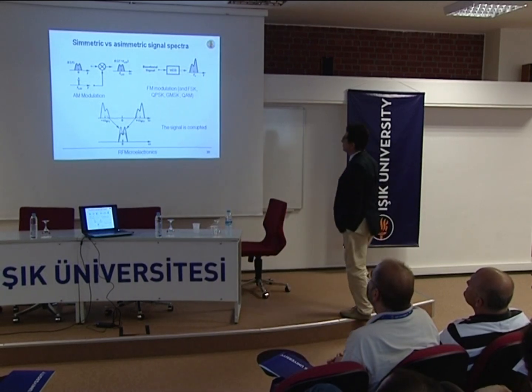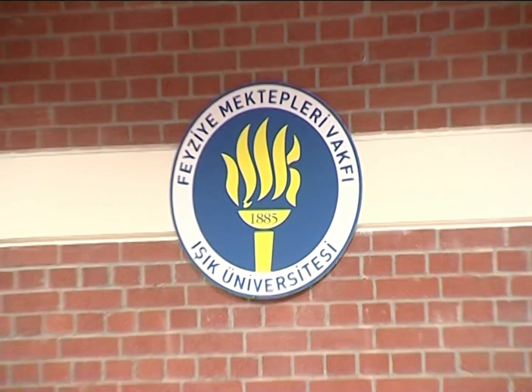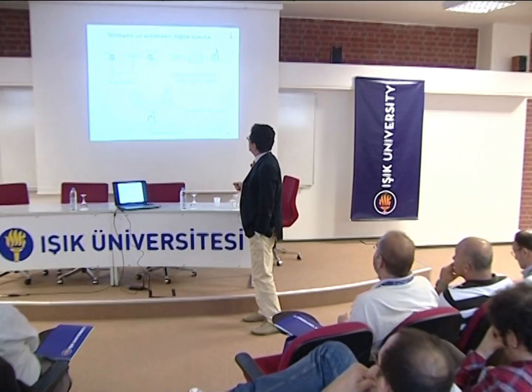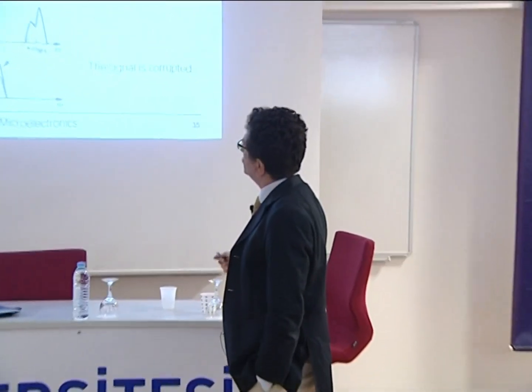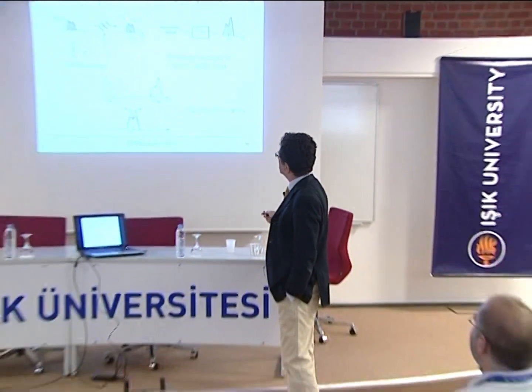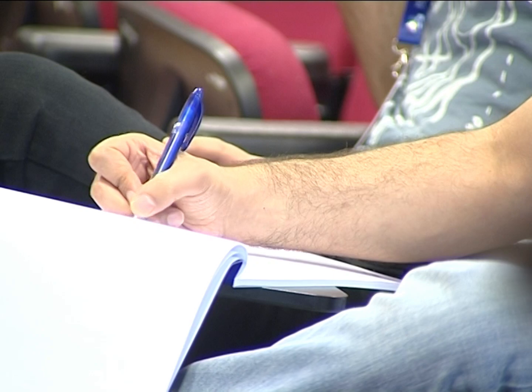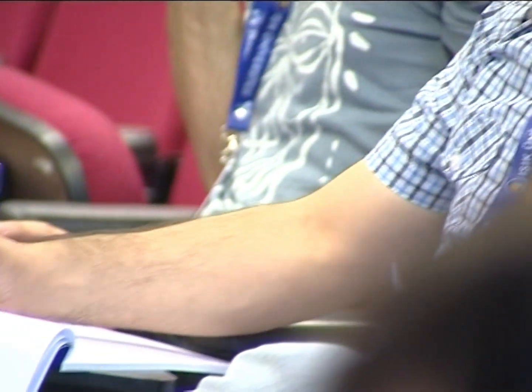This opens the possibility of thinking about an AM modulation, which keeps the shape of the spectrum symmetrical, because we can think about an AM modulation just as a multiplication in the time domain using a mixer. So we start from this spectrum and we result in a new spectrum. I have the positive and negative sides of the spectrum.